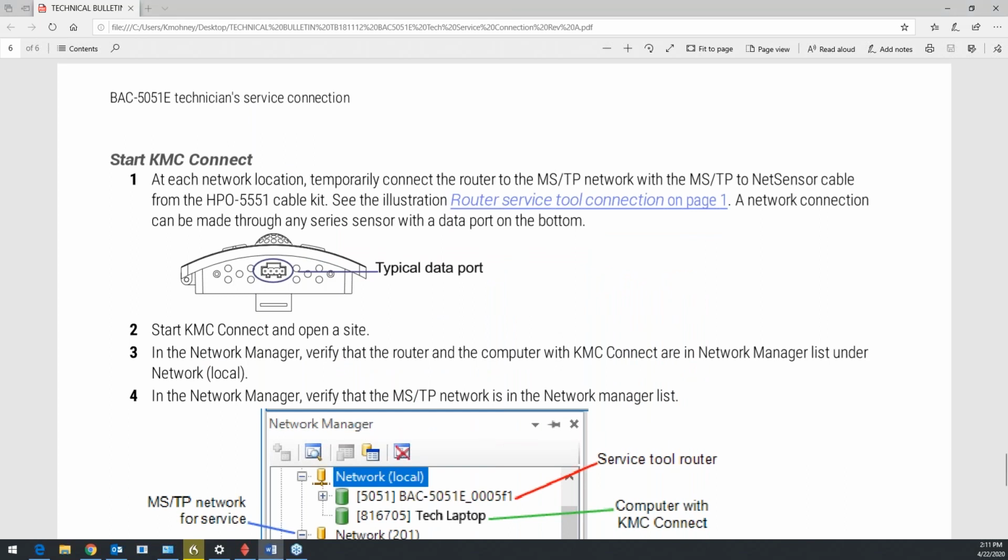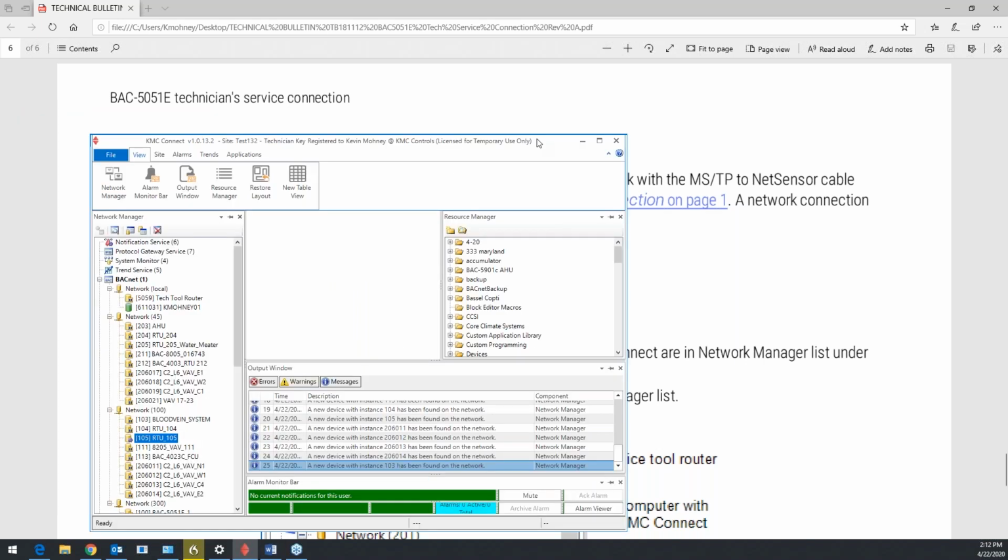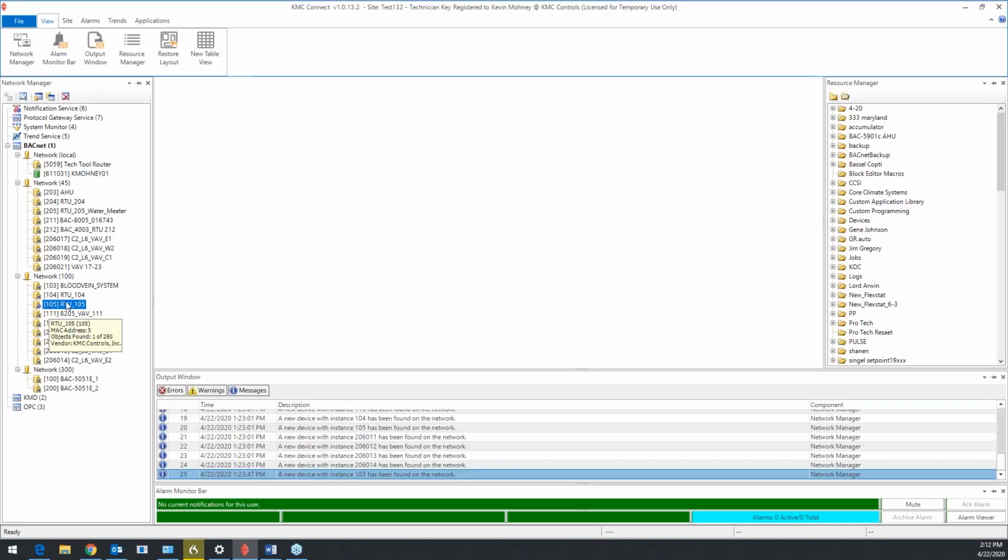Okay. So one good follow-up question here, going back to Connect, is what information is discovered when you have limited discovery enabled? Okay, so let me show you. It just discovers the name and address of each controller. It doesn't discover all the objects sitting underneath it. So you get a network layout with all their names and addresses, but you don't get any objects.